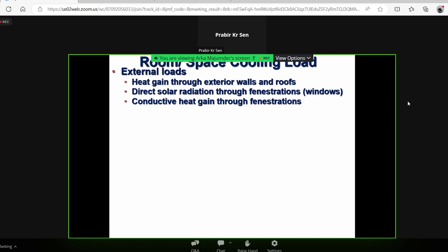And that hot wall radiates inside the room. But the glass window, if it is there, lets a portion of the heat come directly into the room, with the sun directly coming in through the window. Additionally, the window also gets hot and radiates heat inside the room. So glass windows have a double effect, and the walls or roof have a single effect.